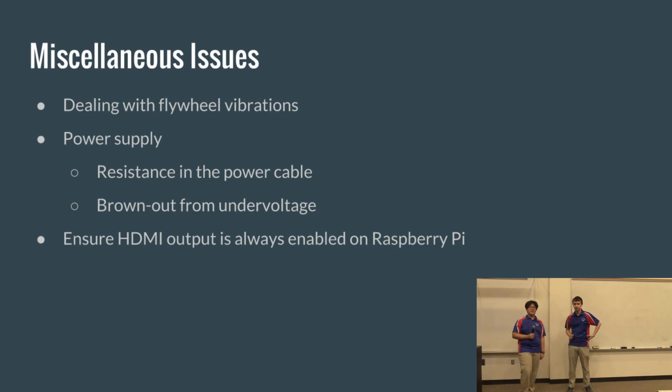Also, have a wide angle view, because at the heart of it, we're trying to get the most things in the image as possible, so we can get the target in the image. If you have the target, you can center on it. But if you don't have the target, then image processing isn't going to really help. You can't find something that's not there. So in general, wide-angle cameras with fairly flexible software that let you set values that you might need to.